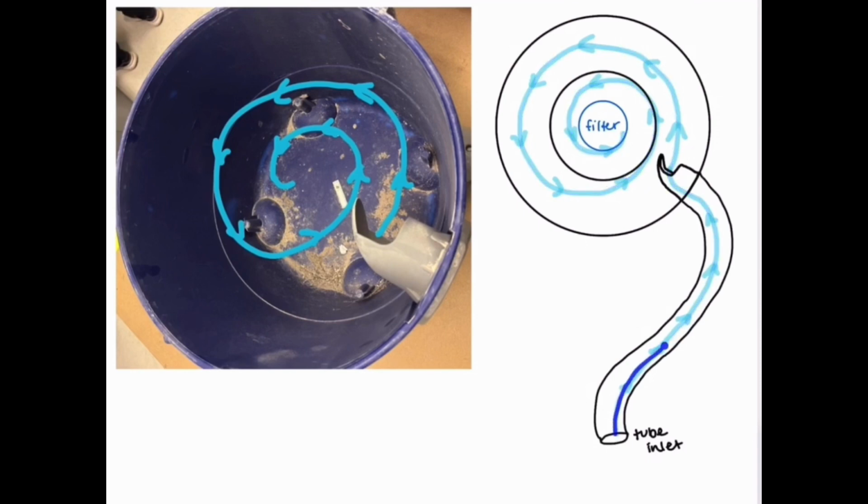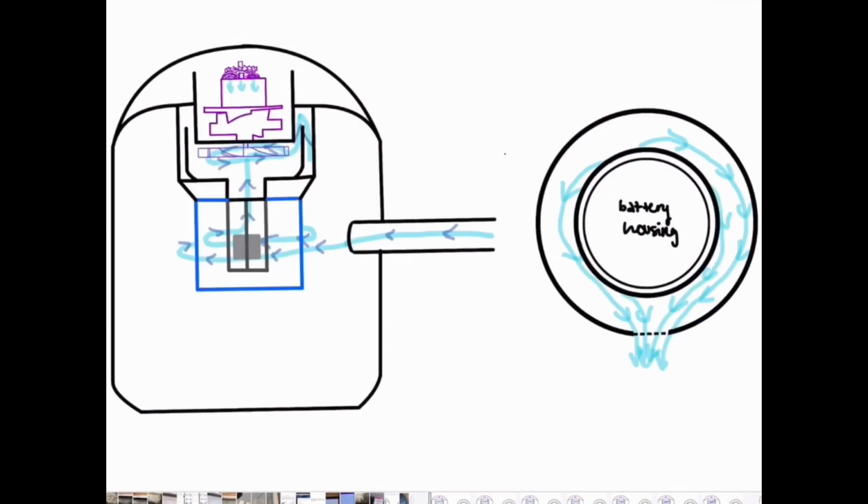The inlet of the collection bucket has a hooked vane, which causes the flow to have a rotating circular path. This circular path allows time for the water or suction debris to fall to the bottom of the bucket and allows for all parts of the air filter to be utilized. Once the fluid has passed through the filter, the fluid accelerates towards the radial fan, where the fluid enters the fan through the center, follows along the vanes, and is radially accelerated up and out of the fan chamber into